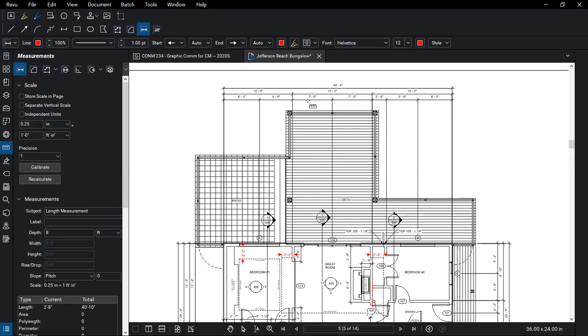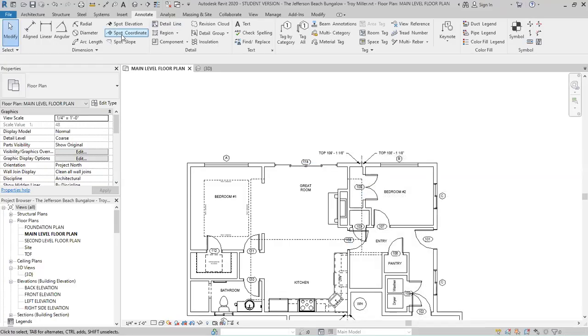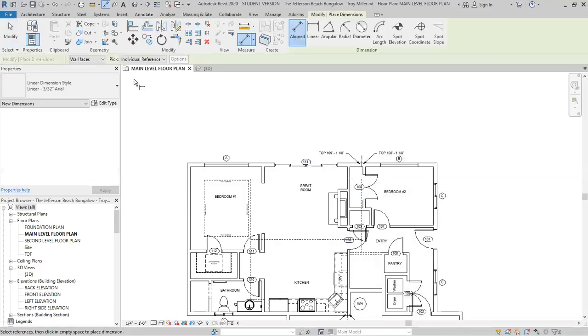And then the next tier out, what we've got going on is we're eliminating the actual windows, and we're measuring from outside of wall to interior wall to interior wall, interior wall. In fact, we don't go to interior wall, and that's the next one. We go from that wall all the way out. And then we have the overall dimension. So to place those dimensions, we're going to come back up here. We've done this quite a bit so far.